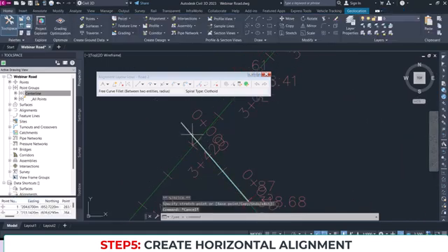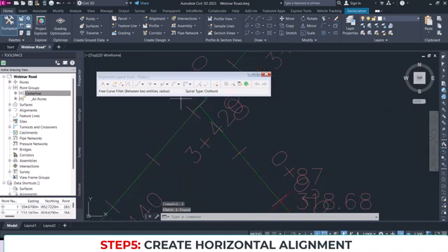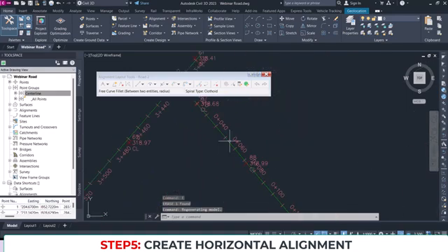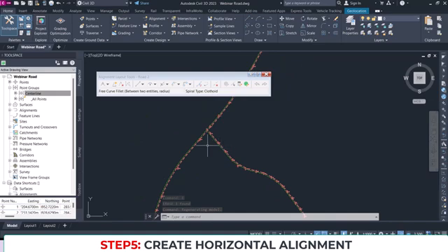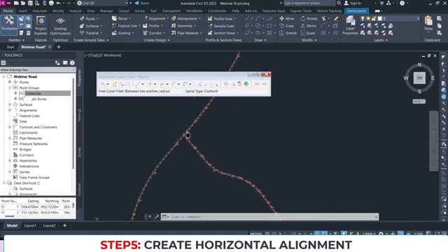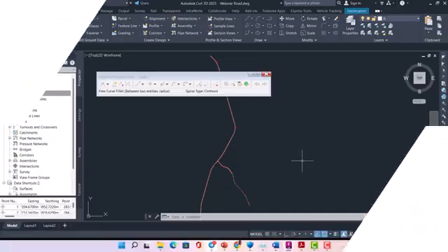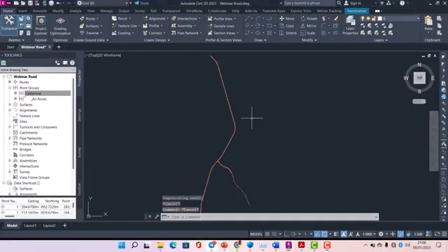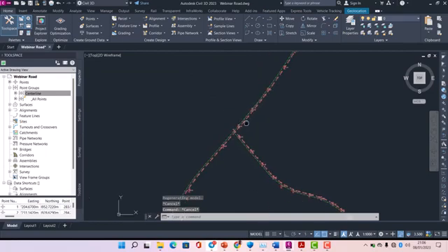Great. So then I can delete my polyline. Make sure you have stretched it to intersect without interfering with the alignment. So great, that is it. We can now move on to creating our profiles if we are satisfied with the alignments and have completed everything. All right, so let's close this. Now we have to go to creating our profile.